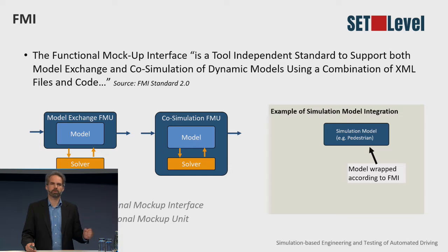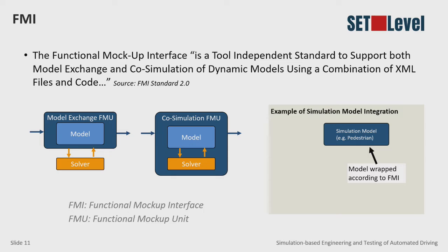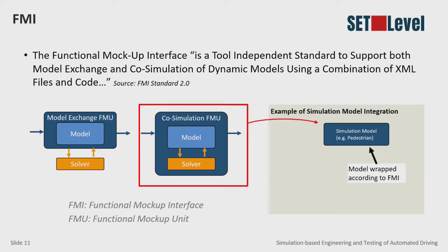And in respect to FMI, this means, is a solver which might be needed in connection to a model. Is it included in the functional mock-up unit, or is it excluded? And I will not go into details about the differences between those two ways of compiling an FMU, but when we talk about FMUs in the context of set level, we always used co-simulation FMUs. So if you see in the architecture views those blue boxes, it's that.